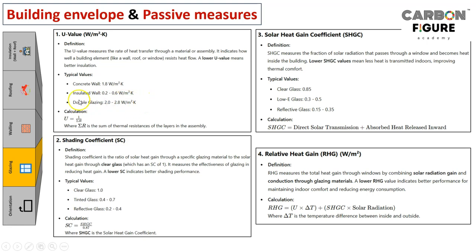So just to keep the passage of heat outside of the building, you can't completely surround it with concrete wall, right? You need windows for whatsoever reasons. So you should understand glazing of one thickness has some amount of U value. Double glazing has a different U value, and triple glazing sometimes people may choose, and depending on the thickness of the glazing also, the price of the glazing system would vary, right? Because double glazing means, we will have a visual in the next slide.